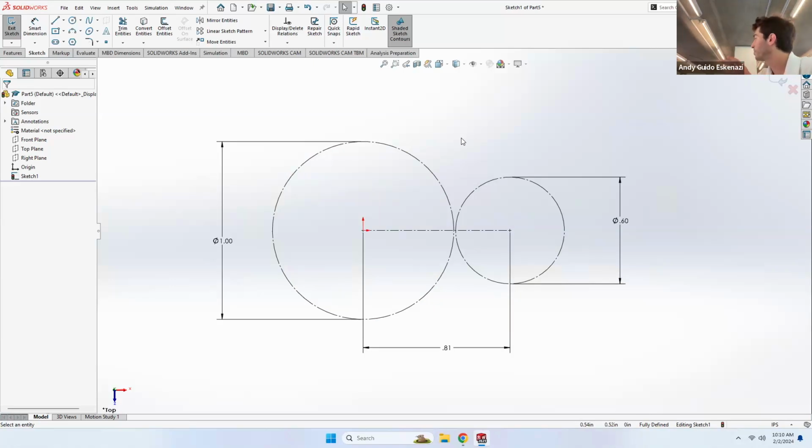And this one will be our master sketch. In fact, everything that we'll do today will be based from this sketch again. And what I like about this is that it's already telling you a bunch of information. First, that if this is your main gear and that's a dependent gear, then you have a gear ratio of 1 to 0.6, right? So for one rotation of this one, this is going to rotate 1 over 0.6 times. So that is a little bit less than twice. I don't know, it's like 1.8, 1.6, something along those lines.